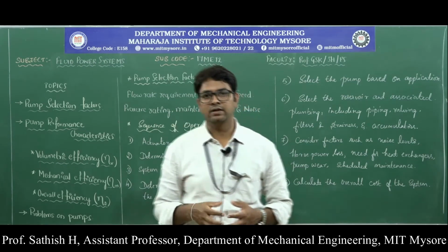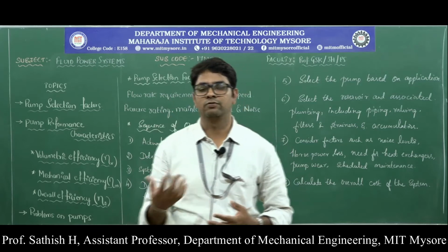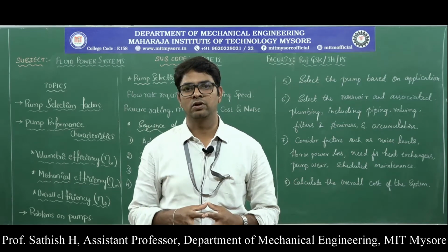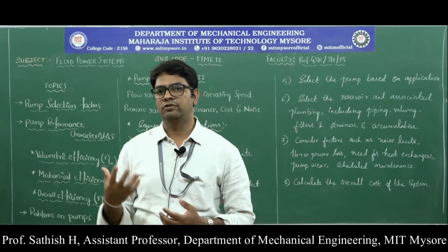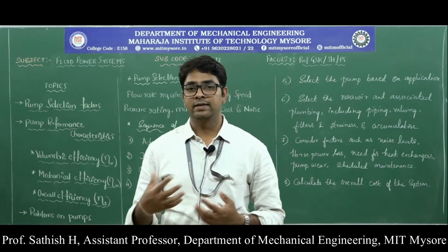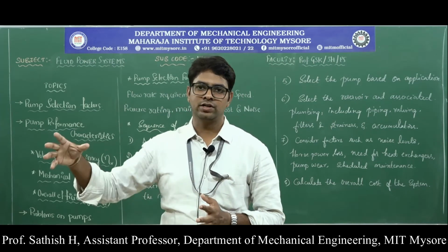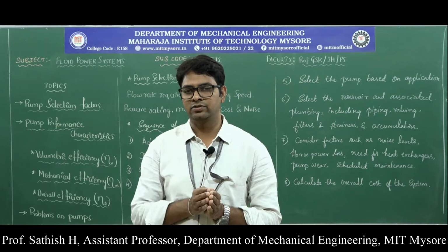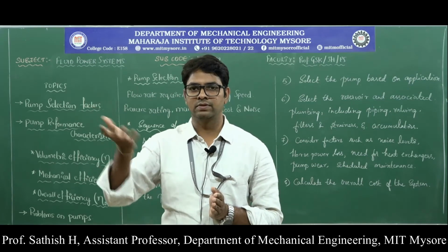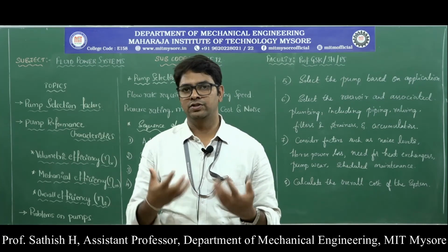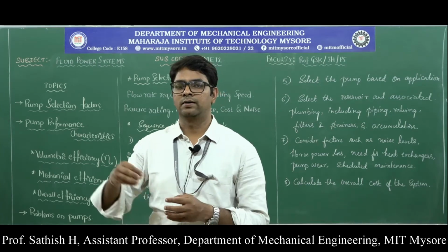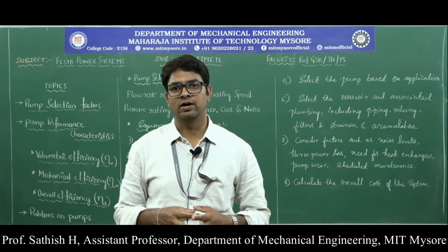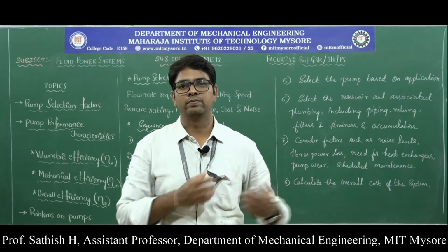Pressure rating means how much pressure the fluid power system or hydraulic system operates with after designing everything. That is also very important. The pressure of the fluid is required because there is resistance to the flow of fluid: at the actuator we apply the load, and the fluid has to move against this resistance and take that load through some distance, for example. So the pressure is proportional to the amount of load the fluid power system is lifting.